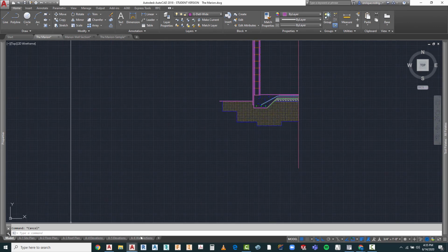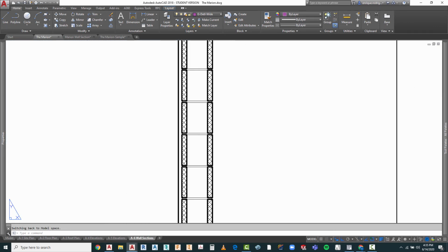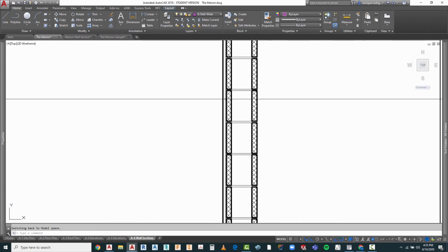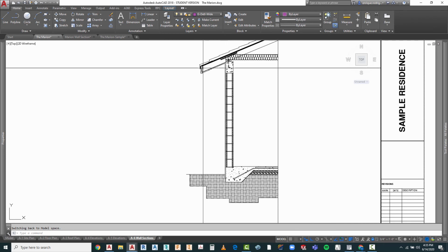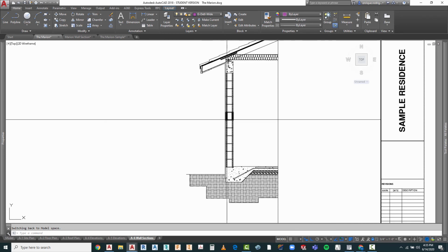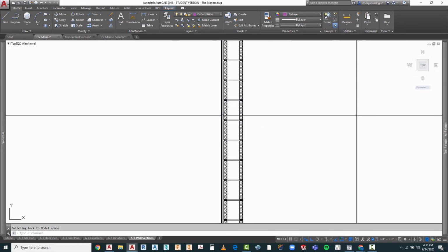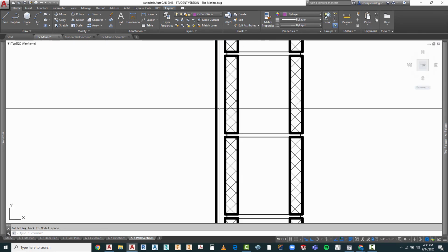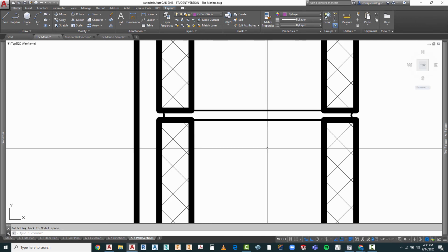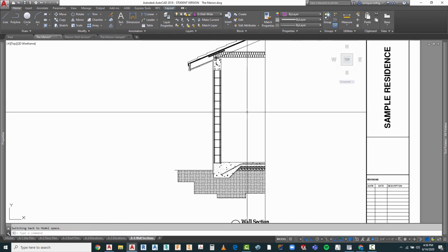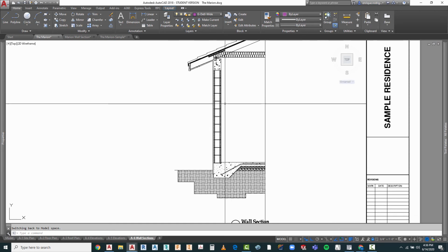Now if you wanted to add a hatch to that, we could. I have no problem leaving it the way it is. We could do this at 3/4 of an inch; I did it at 7/8. So if you do want to add a hatch pattern, a dot hatch pattern would be good. Just think about the thickness of the layer when it prints. Remember, dots are very difficult to see if you put them in too thin of a layer. So there's a little fine balancing that you need to do there. All right, let's go ahead and finish up doing the inside.